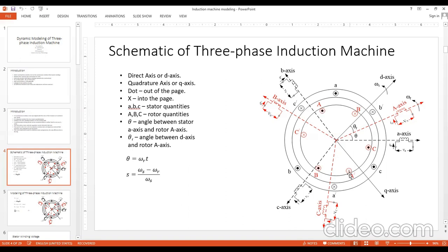The capital A prime, capital B prime, and capital C prime are the representatives for the rotor coils. Once they have the induced voltage, as per the construction of the wound rotor induction machine, we have to either use three-phase resistive elements in the three different phases, of course in a balanced manner to keep things balanced, but ultimately we have to short out the ends. Either you can go for some finite resistance, or you can simply short circuit the three-phase coils available in the rotor circuit. The reason is that we actually want current to flow in the rotor coils.